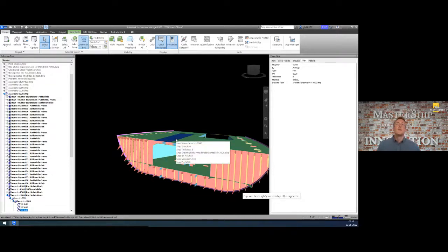And if you click a part, here I click now the deck plate, and you already see the MasterShip information. I hope you can see it via the stream. Here on the right, you can see the part identification number, the section number, the thickness, the material, and the drawing from which it originates. But there is more information that you can get. In fact, all the information stored in the MasterShip database, so each part has a lot of meta information in it, you can get, if you like, into your Workshop Assistant.